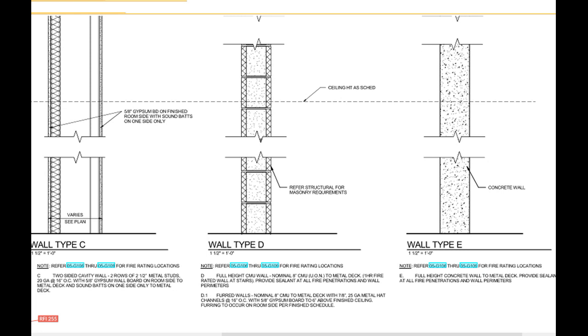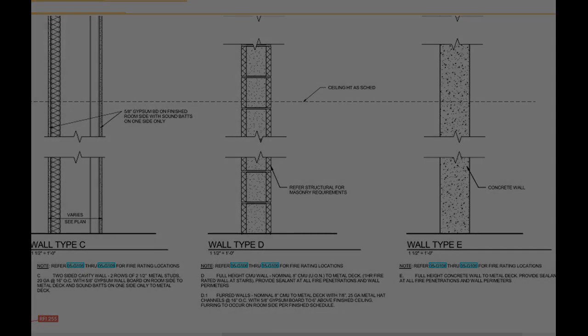Internal walls typically fall into two categories: load-bearing walls, sometimes referred to as structural or solid walls, and partition walls. Load-bearing walls are constructed from mortar-bonded masonry in the form of fired clay bricks or concrete blocks. Partition walls can be solid, typically constructed from brick or blockwork, or can be a framed construction. Framed partition walls are sometimes referred to as stud walls, and can be constructed from timber, steel, or aluminum frames clad with boarding such as plasterboard, timber, metal, or fiberboard.